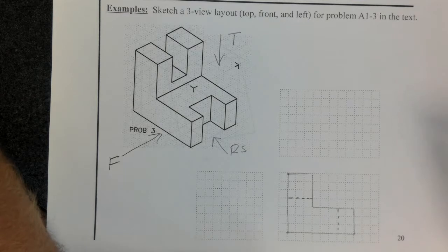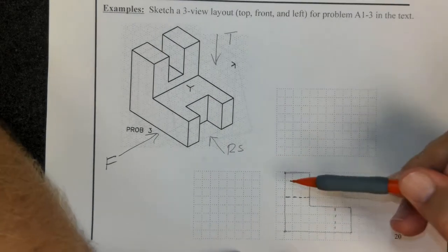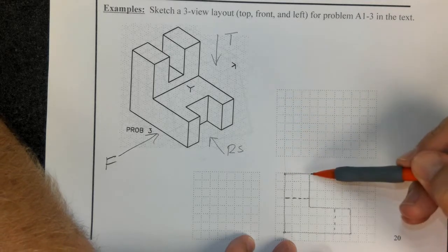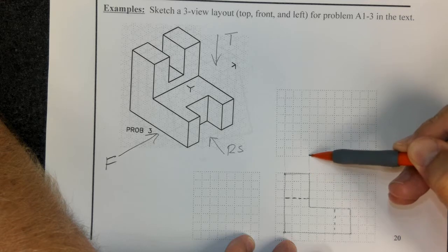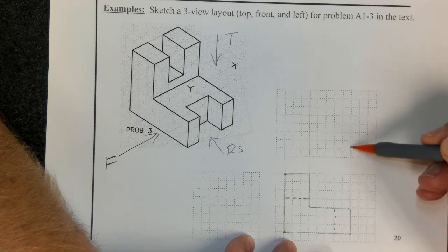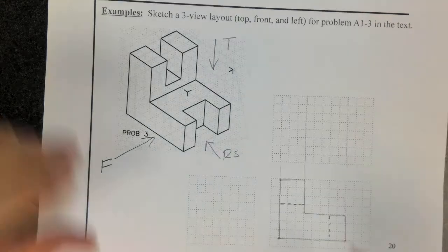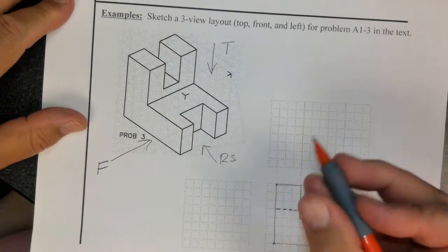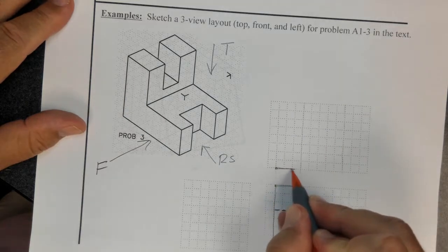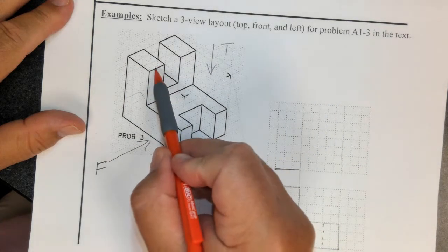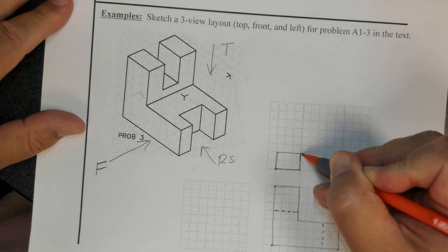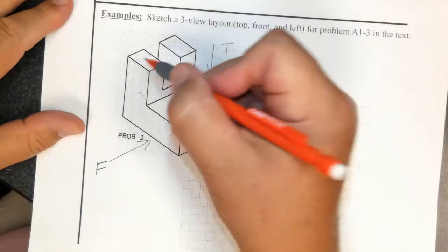Now, the method of projection. I'm going to take every one of these intersection points here and lightly draw a line upward like this, okay? Here's another intersecting point. Draw a line straight up like this, and then here's one. Draw a line like this, okay? So I'm going to start off with this point. So this would be that point right there. And again, we come 3 units, okay? And then we have 1, 2. Okay, so that's this surface right here.